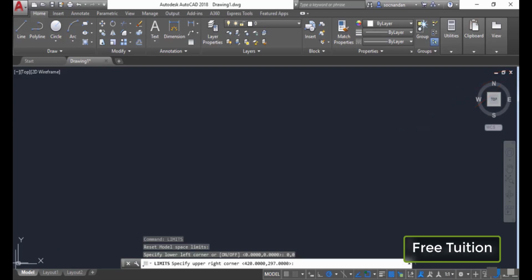So you can see that the lower left corner values are 0, 0 and the upper right corner values are 420, 297. That means the length of this screen should be 420 units and the height should be 297 units, whatever the unit of the current drawing is. But that's not always the case. In this case, the height is obviously 297, but depending upon the aspect ratio or the screen resolution or the size of the screen, your length may differ. So if you want to accept the value, simply press enter.